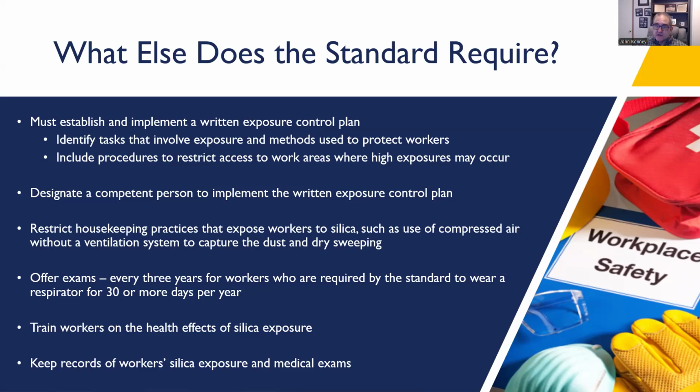So again, you can see this follows the same guidelines as many other OSHA requirements. Restrict housekeeping practices that expose workers to silica, such as the use of compressed air without ventilation to capture dust and dry sweeping. So, very important.